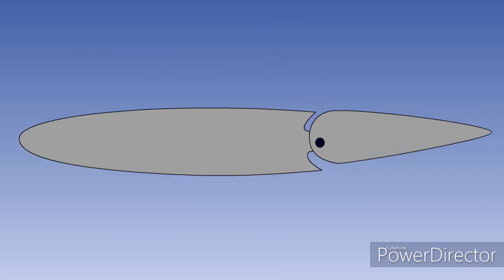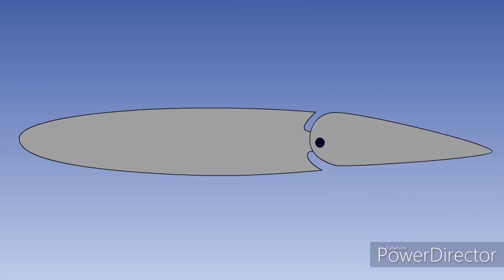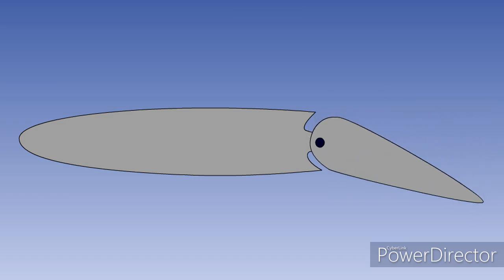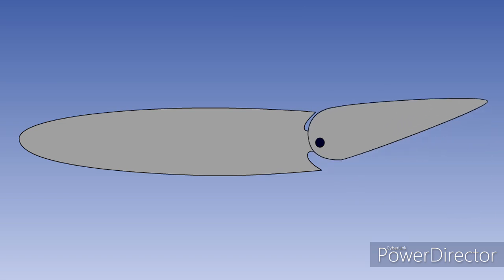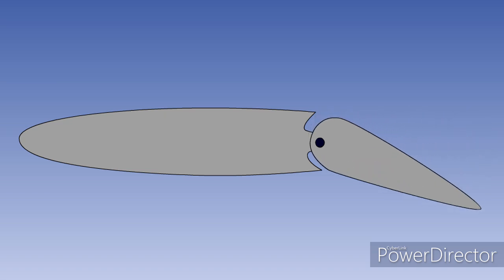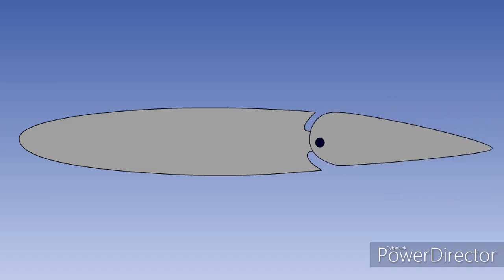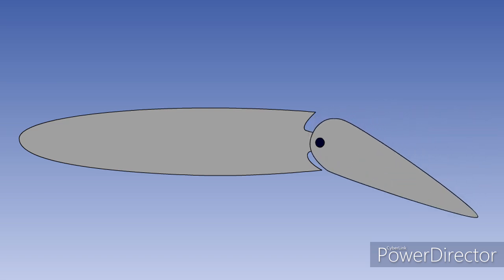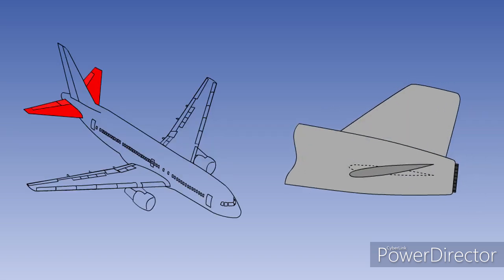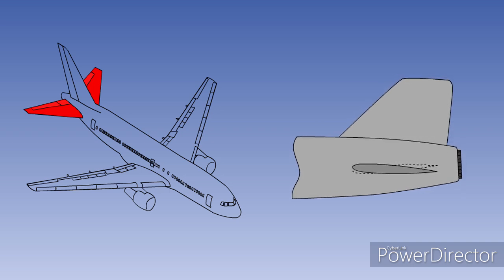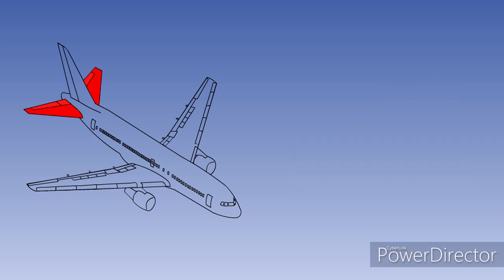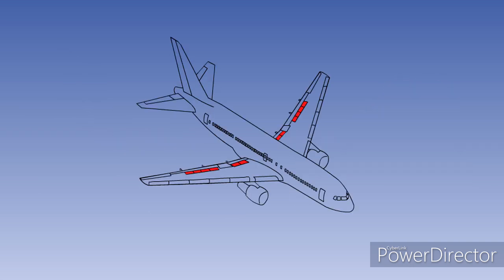The movement around an axis is produced by changing the aerodynamic force on the appropriate aerofoil, wing, tail or fin, and this may be done by changing the camber of the aerofoil by deflecting a control surface, changing the angle of attack or incidence of the aerofoil, or decreasing the aerodynamic force by spoiling the airflow.